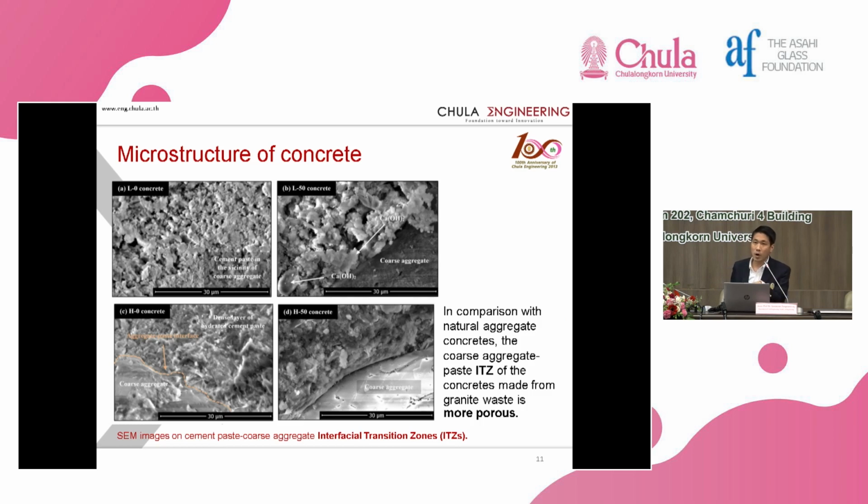After that, we want to have some more understanding. We go to the microstructures, and what we found is that the interfacial transition zone, or ITZ, when we had the granite replacement, you're looking at the bottom diagram on the right-hand side, you see a little bit of void, which shows that when we replace the sand with the granite particles, we have some micro voids in the concrete. So that's why we might have to take into consideration the long-term effects and corrosion, which we present as future work here.